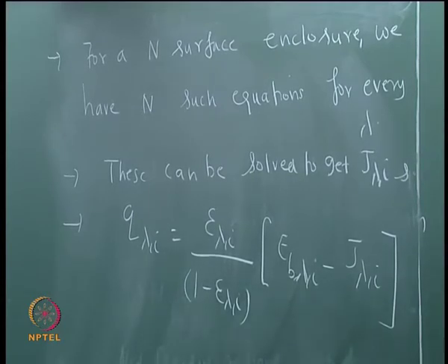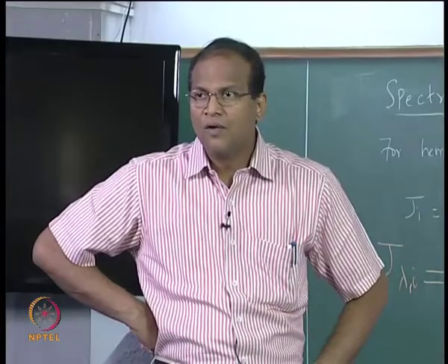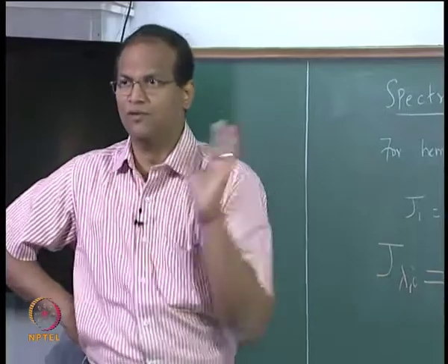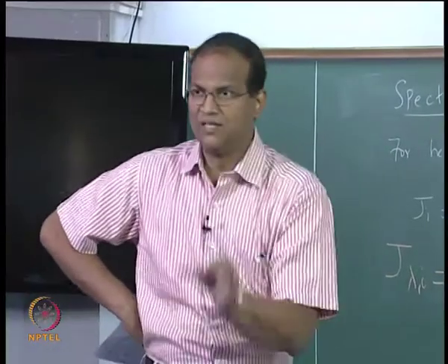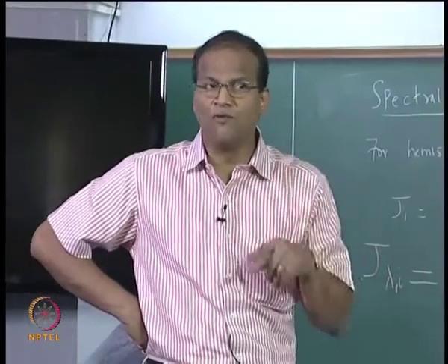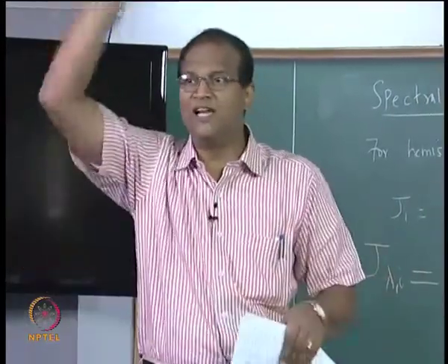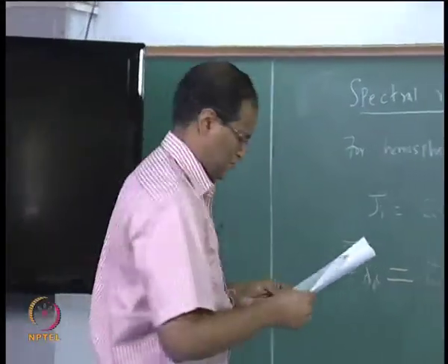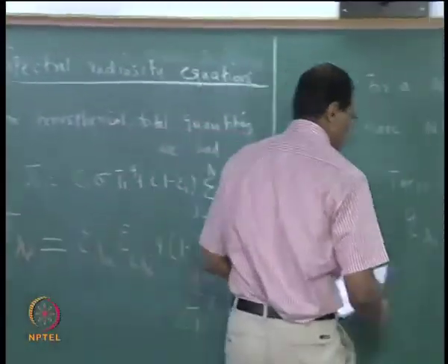What is that E b lambda i? It will be the F function in that wavelength interval multiplied by sigma T to the power of 4, only that much. That E b lambda i will become sigma T to the power of 4 if the J lambda is replaced by one general J which we used in the previous classes, correct? What is the key point here?